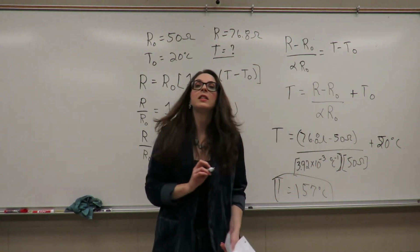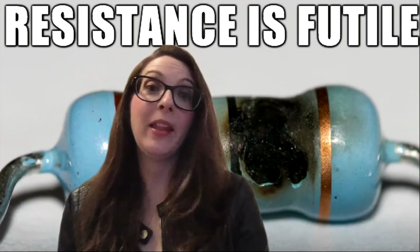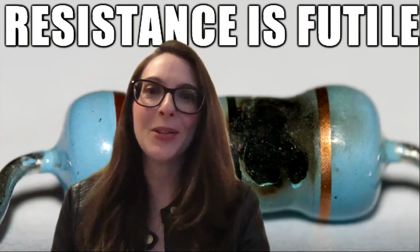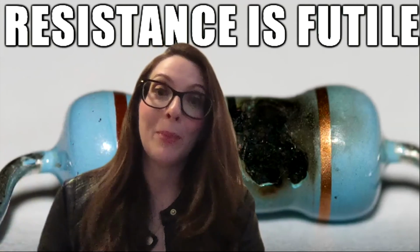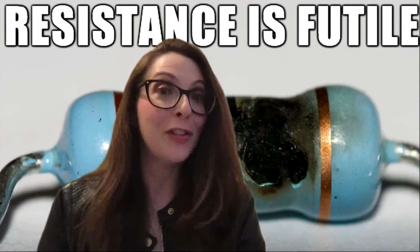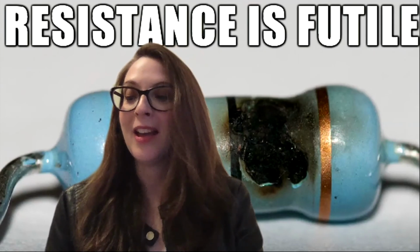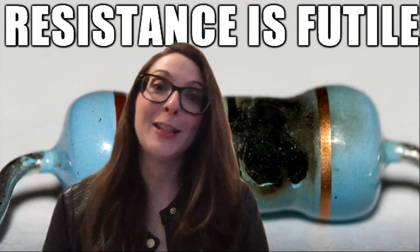is 157 degrees Celsius. So we've approached near the end of our mini lecture about resistance, and I wanted to put this quote behind me, which appears to be chopped off a little bit, but resistance is futile. And behind me here is a resistor that has literally burned up on itself. So this resistor has severely overheated, if you couldn't tell. When a resistor is placed under a voltage that approaches the upper limit of its power rating, the resistor generates more heat than normal, and this is an example of that.